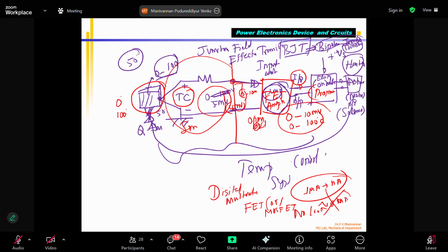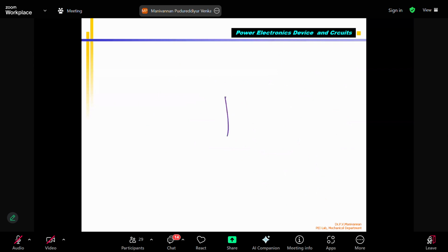And it has an advantage. What is the advantage? It avoids the loading effect. Wherever you want, already we saw about the op-amp, right? Op-amp we already know. We saw that extensively. Nowadays we are using op-amp. Now an op-amp can be made with transistors. I already showed the internal circuit diagram, correct? UA741 I showed you. It has a differential amplifier. After that, many stages are transistors.